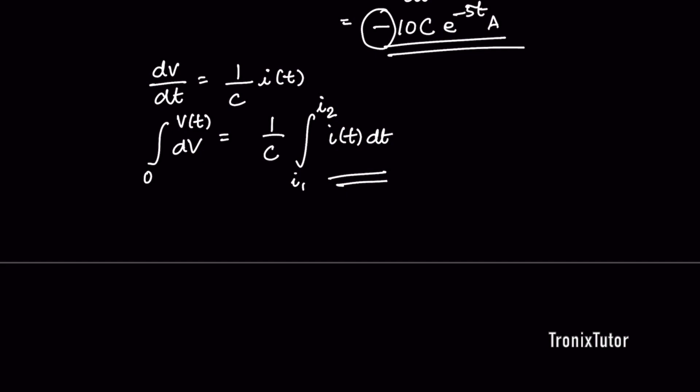Now, suppose the capacitor was initially charged to some voltage, then if a current flows, so for example, suppose here is a capacitor, and suppose this was charged to some initial voltage V0. Now, if a current flows into this capacitor, then we expect this V0 to increase. However, if we have a condition where the current is flowing out of this capacitor, then we will expect the V0 to reduce. Right? And that is essentially the charging and the discharging process.